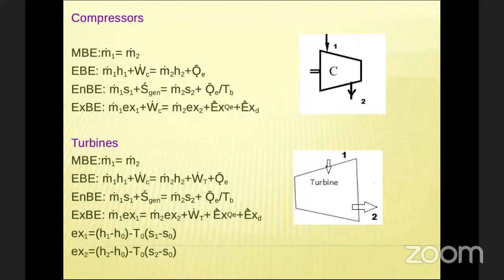Using in the thermodynamic systems, for the pump the mass balance equation will be ṁ1, you know, whatever water you are extracting, the same water is coming out. So ṁ1 equal to ṁ2. And what is the inlet? From low grade, we are lifting to the high grade. So ṁ1 h1 pump, which needs the energy input, so which will be on the left side. Ẇp. This is equal to, combinedly used to lift the water, ṁ2 h2. What is the pump work formula? We know that ṁ v into Δp. Okay, so that is ṁ v into Δp, where Δp is p2 minus p1.